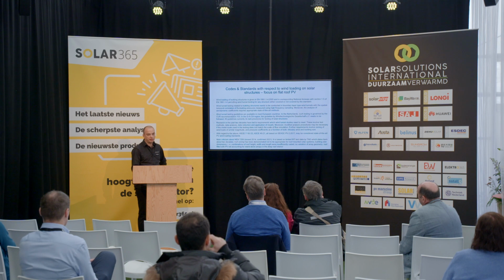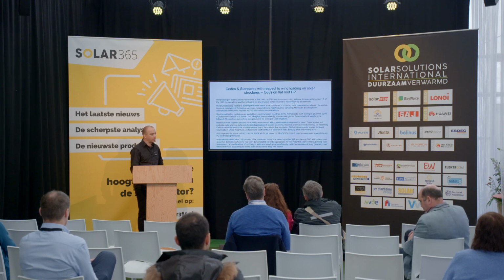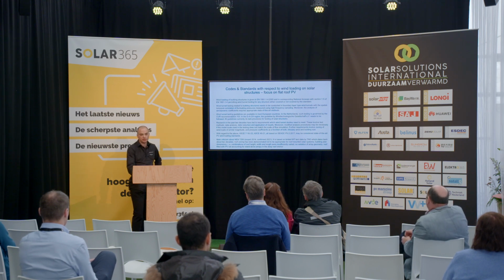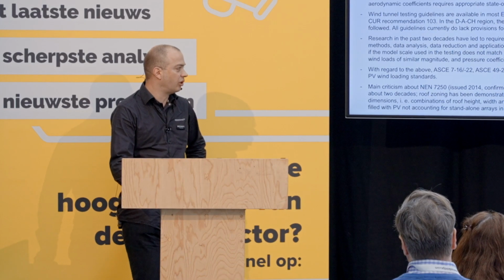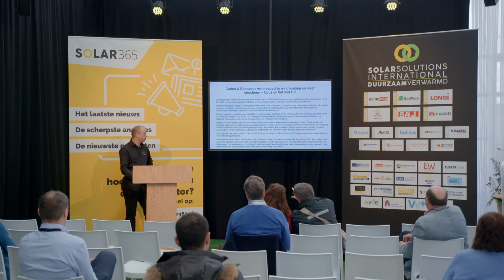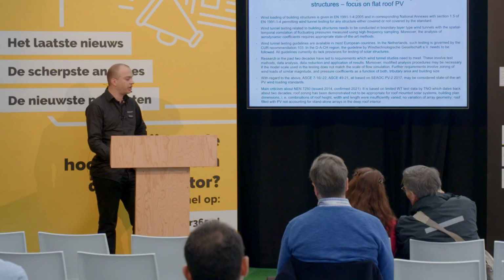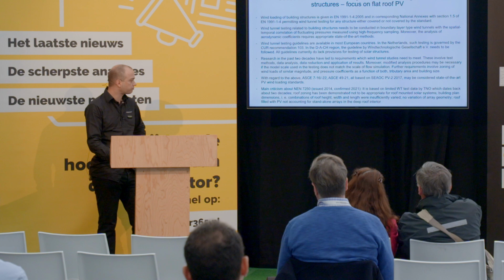Moreover, there are modified analysis procedures which may be necessary if the model scale used in the testing does not match the scale of the flow simulation, and that is mostly the case. Further requirements involve zoning of wind loads of similar magnitude and pressure coefficients as a function of both tributary area or load sharing and building size.